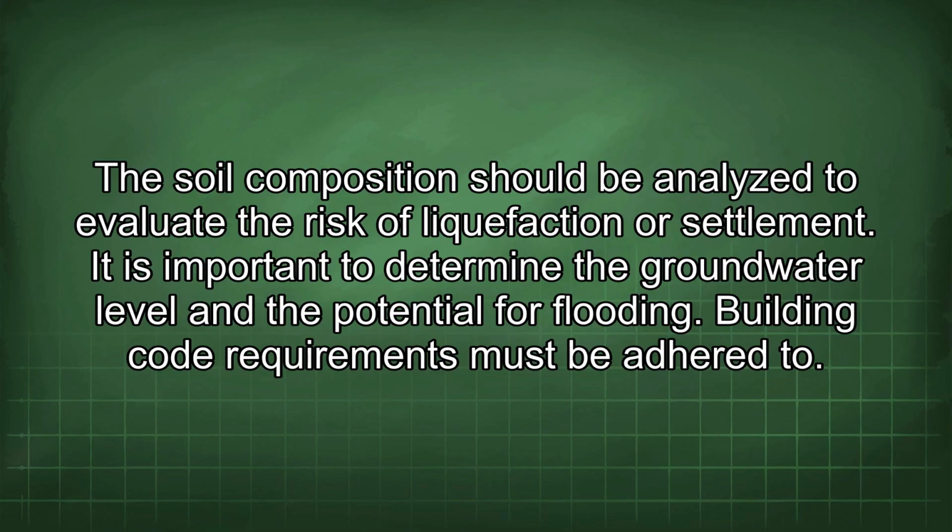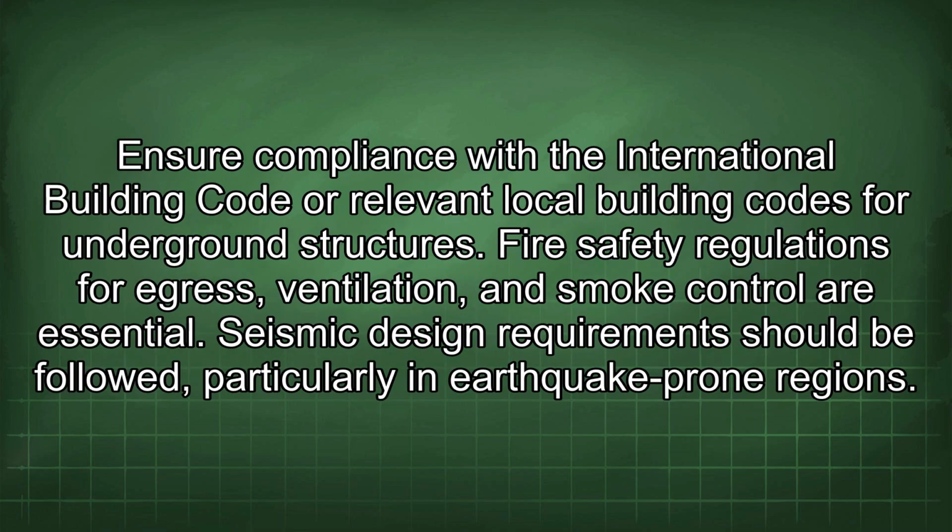Building code requirements must be adhered to. Ensure compliance with the International Building Code or relevant local building codes for underground structures. Fire safety regulations for egress, ventilation, and smoke control are essential. Seismic design requirements should be followed, particularly in earthquake-prone regions.